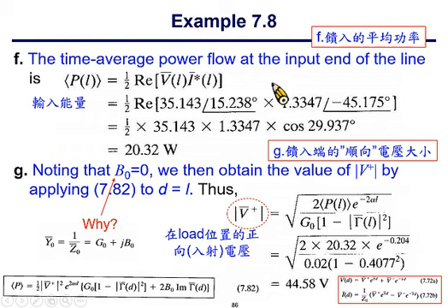The key point of this problem is that you need to understand what the symbols and parameters here stand for. This parameter refers to the positive voltage V plus at the far right end. So this one stands for the voltage delivered to the load, to the termination. Using this equation, you can have this expression. Modify the equation a little bit.